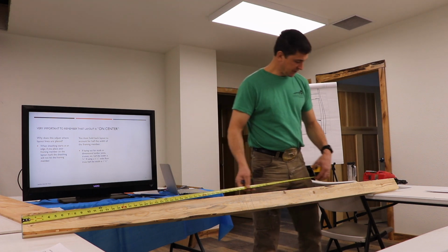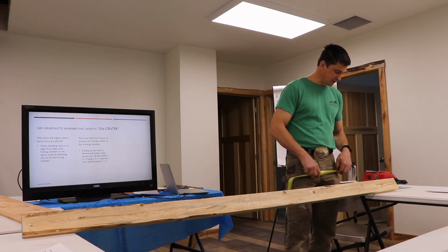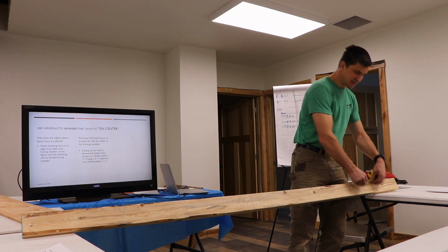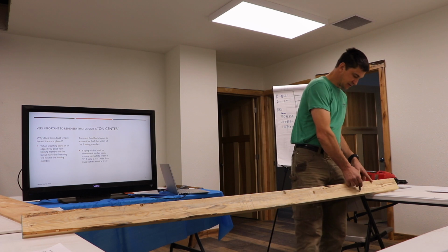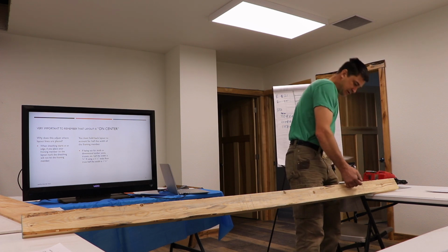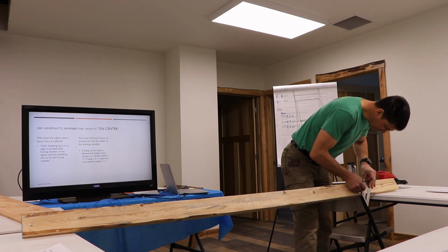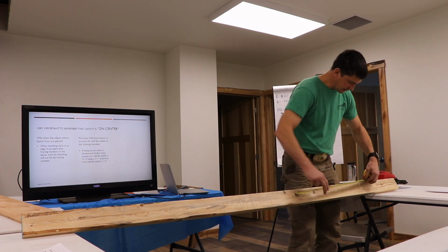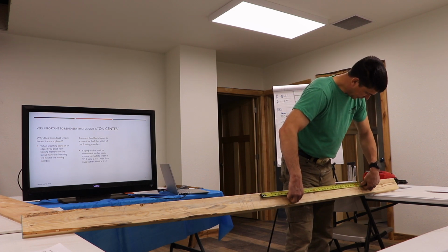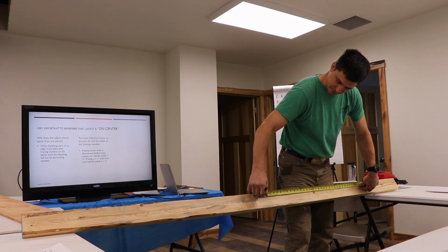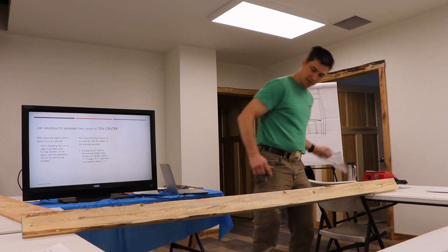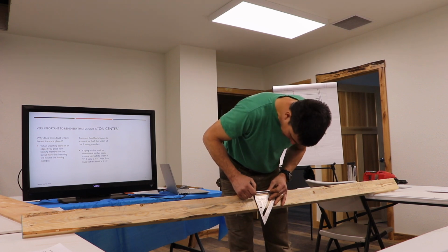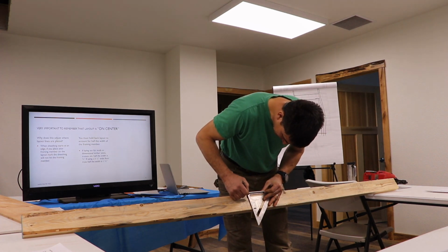like you have the option, you lay it out exactly like the plan shows, and you're like, boy, my layout comes right there. That's 7/8 of an inch. I'm just going to scratch these out, and then I'm going to go like this, and I'll put my shoulder there, king stud there, and then I'll measure my 32 7/8, and we'll scratch those out, and I'll remark them here. Sometimes those scratch out marks get pretty big.